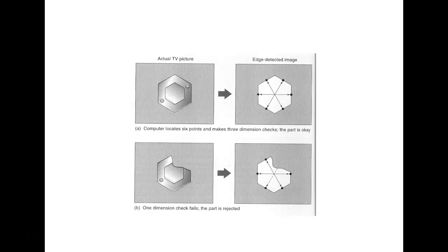So what we have is a test pattern that we put down where we want it to vision in, and then we come in and calibrate that camera. So you're right, most of these cameras have to be calibrated. And once you get it calibrated, then you just point it at whatever object you want it to learn, and the camera literally memorizes that. And when it picks that object up, it would actually send XYZ coordinates into the controller, and the robot just went to that spot. Sure did.